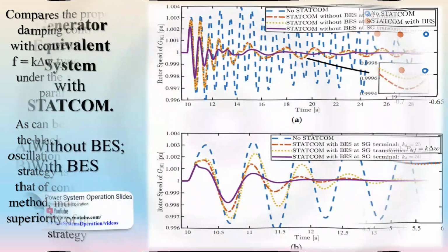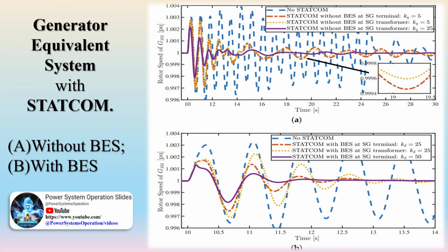Modes of operation. The STATCOM can be operated in two different modes. Voltage regulation. The static synchronous compensator regulates voltage at its connection point by controlling the amount of reactive power that is absorbed from or injected into the power system through a voltage source converter. In steady-state operation, the voltage V2 generated by the VSC through the DC capacitor is in phase with the system voltage V1, delta equals 0, so that only reactive power Q is flowing, P equals 0.